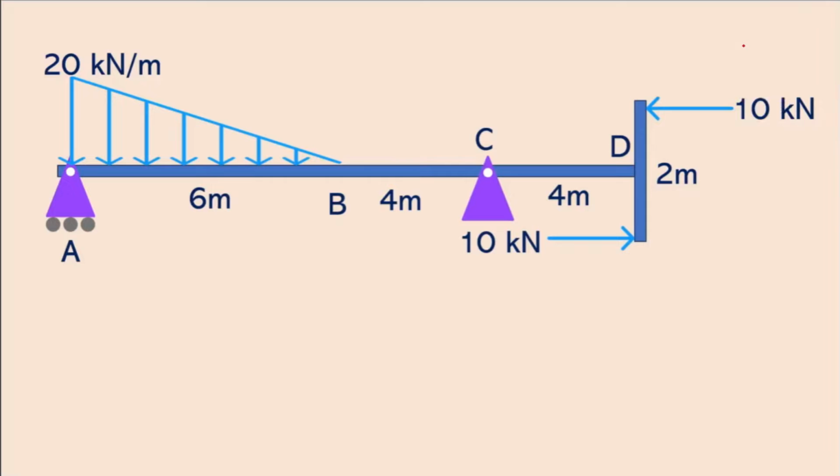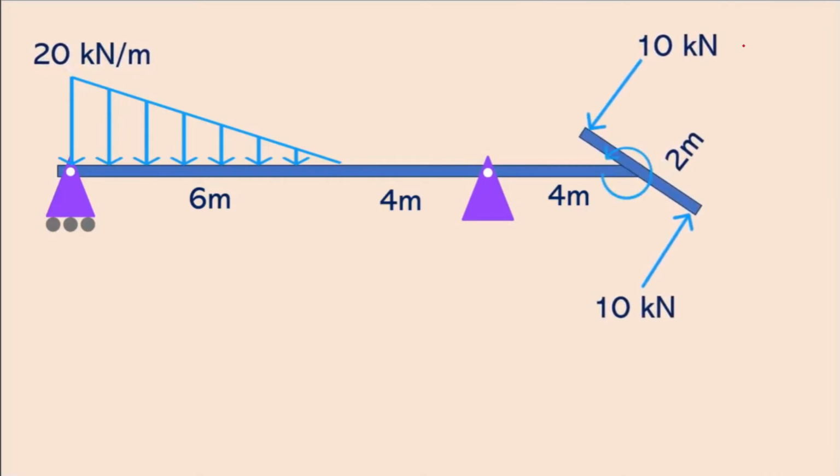And then again, if this will rotate, we can just reduce that into 20 kNm. Now sir, saan galing yung 20 kNm? This moment is just the force multiplied by the arm of the couple. Now our force is 10 kN. And then yung arm ng couple is 2 meters. And so we will multiply this one by 2. And so that's why we have 20 kNm. And then we can just reduce this load. And so ito na yan.